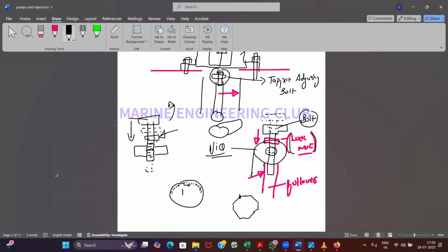If the markings are not given, suppose the marking is not given, what you do is, this will be the plate looking at you. You make markings like this. So every division is how many degrees? From the center, 45. I will make degrees like this, okay? So you can calculate, right? 360 divided by the number of divisions, right? So what I will do, I will make one paint marker on this position.